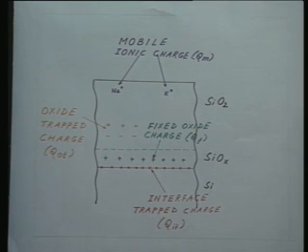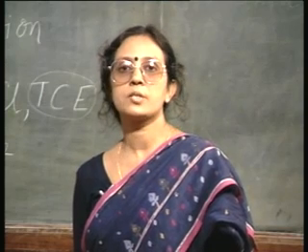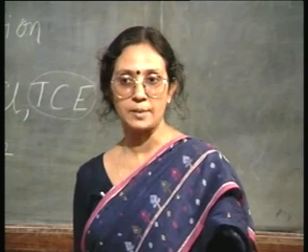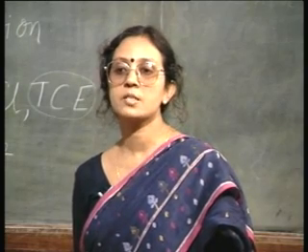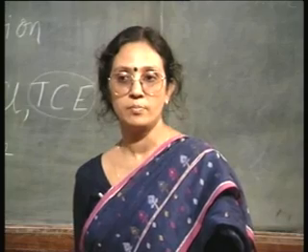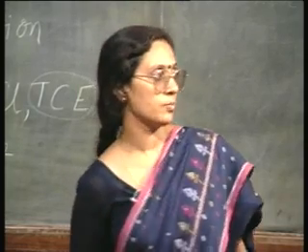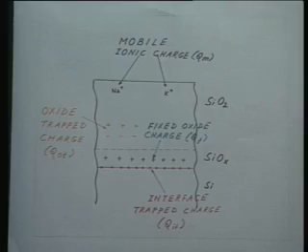That is not to say it cannot form during processing. For particular processing, like for example say ion beam etching, when the semiconductor is being subjected to a focused ion beam, then in that case it is possible that some amount of oxide trap charges are formed during processing itself, but by and large it is after the processing is over and the device is subjected to ambient conditions, adverse ambient conditions, radiation environment and such like, then the oxide trap charges come into picture.